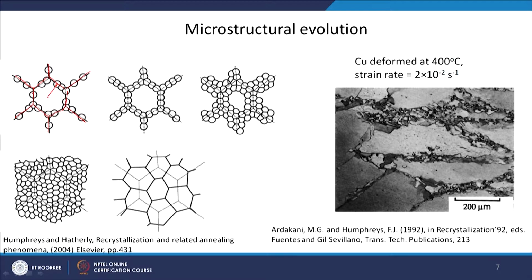Now, since the dislocation density is high as well as you have high angle grain boundaries, when you start a nucleation process, it can be easily done on a high energy site here. Because of that, all the nuclei form at the grain boundary, and it gives you a typical necklace type of structure.